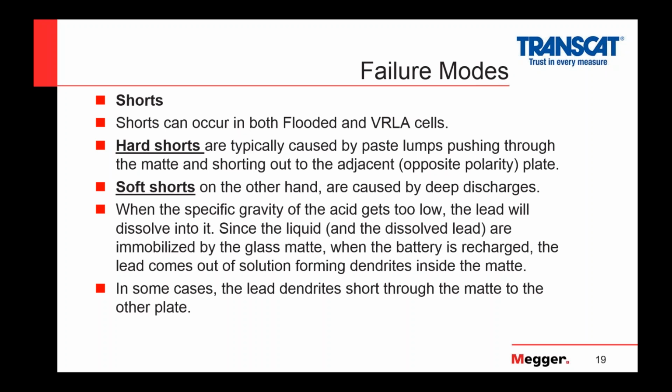Now, soft shorts, on the other hand, are caused by deep discharges. When we discharge a battery, lead-acid batteries are only designed to be discharged down to about the 80th percentile of their voltage, and SLI batteries less than that. Okay.